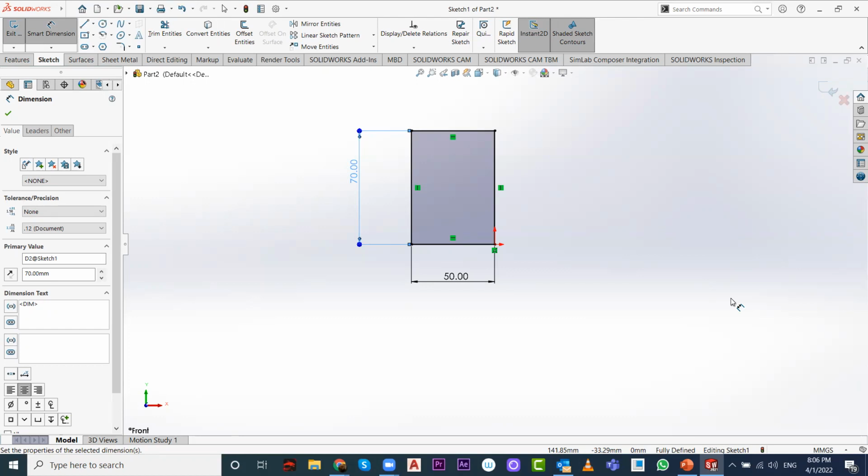And if the first sketch and the first feature is not defined to the origin point, and you want to change or modify, let's say, feature number 26, once you change the dimension of the sketch in feature number 26, everything will be damaged. You will have a lot of errors because the first one is not defined to the origin point. This is very, very crucial.